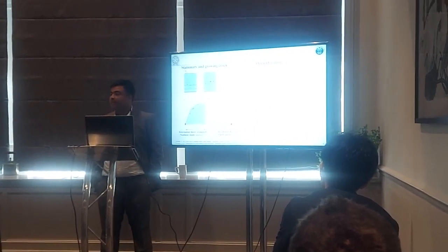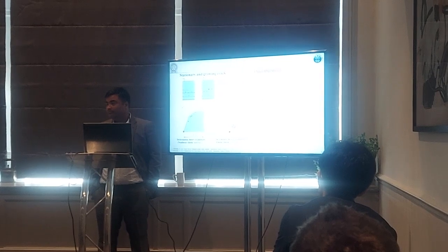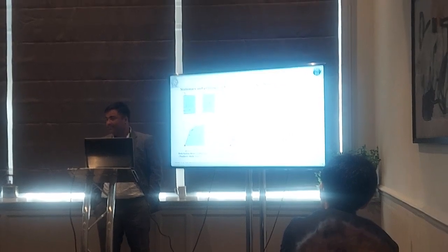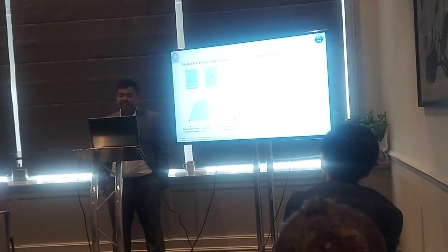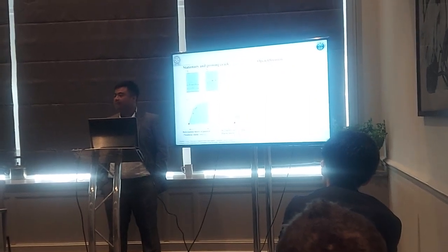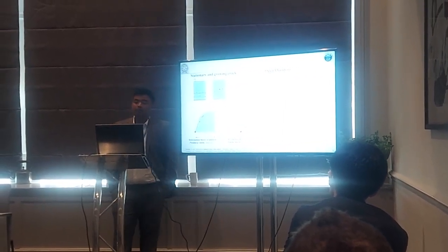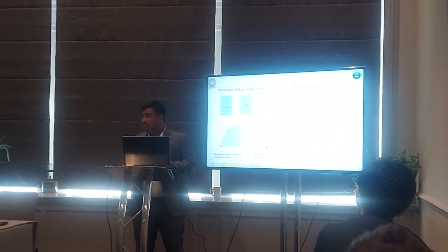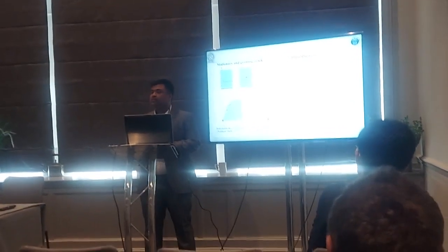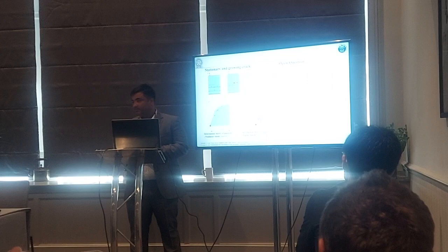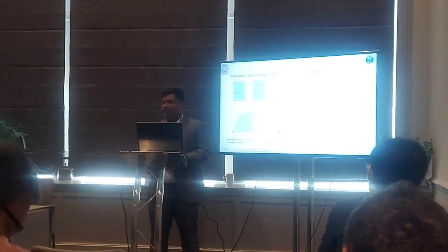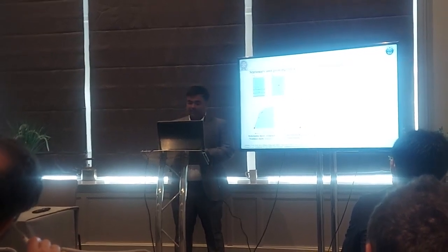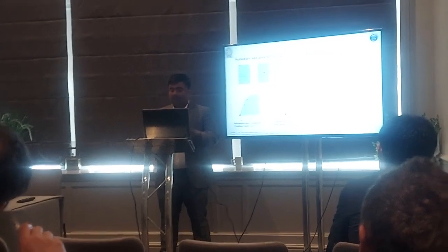Is the application of the C parameter physically sound? C star and CT basically give the driving force, so how do we quantify the driving force of a creeping material, SS316 versus L? Basically C star and CT are not able to tell anything about the driving forces. J only tells about the energy release rate, and C star tells nothing like that. These parameters, the line integrals, are used only to find the stress and strain at the crack tip during a creep condition. But how do we solve these problems?